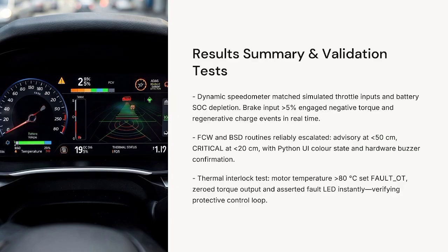Thermal interlock test. Motor temperature greater than 80 degrees Celsius set the fault, zeroed torque output and asserted the fault LED instantly, verifying the protective control loop.